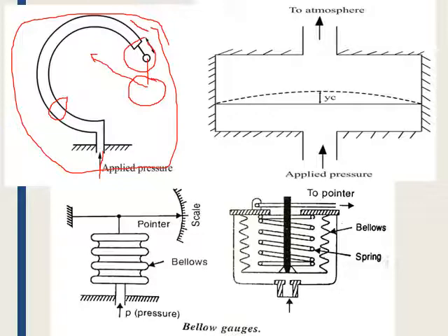When a pressure is created within the Bourdon tube, the Bourdon tube causes the displacement of the link at the end, and that link is connected to the intermediate devices and is then finally connected to the dial indicator, dial gauge, or LVDT, so that finally it can give the reading over a scale of the magnitude of pressure.